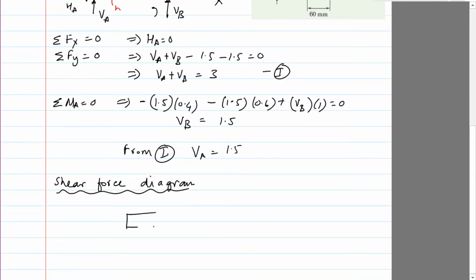So you can start from the left or right. So if you start from the left, you're going to put the external forces, which is 1.5. So let's just write 1.5. And then put V downwards, where downwards is positive by sign convention. And if you want moment, it's going to be positive counterclockwise, and then write the equation.